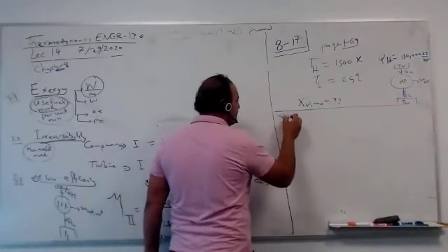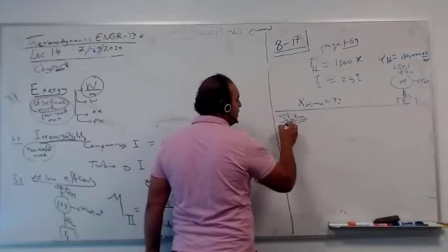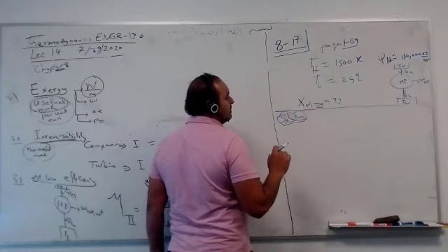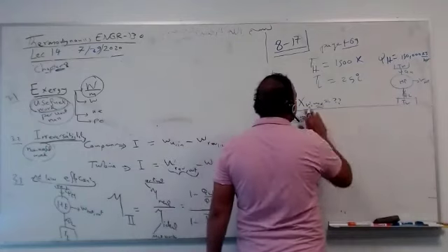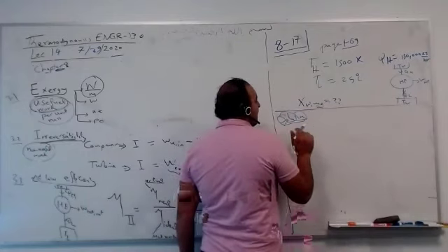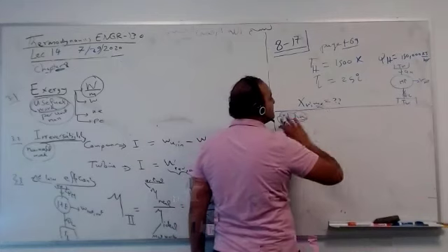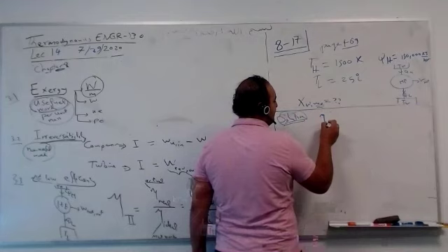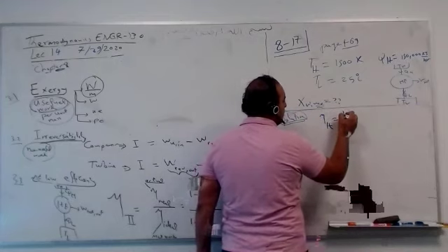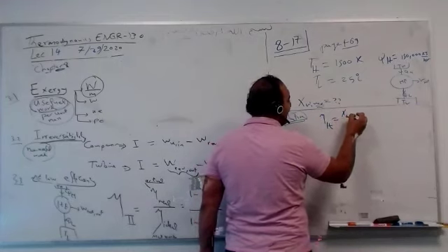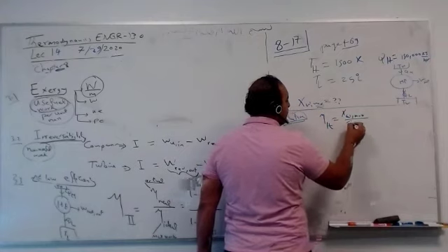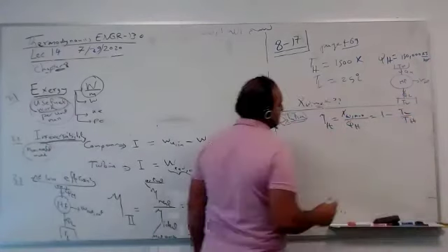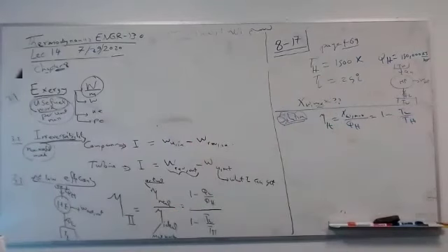Solution, the first thing is, we don't need to use the real anymore. It's ideal. I want the maximum. Carnot, reversible, the most efficient. Ideal process, reversible, isentropic, everything is pure here. So it means eta thermal, for example, is work, which is exergy, maximum, over Q high, equal 1 minus T low over T high. We are done. That's it.